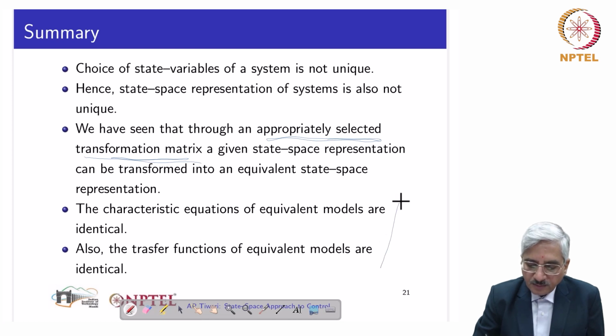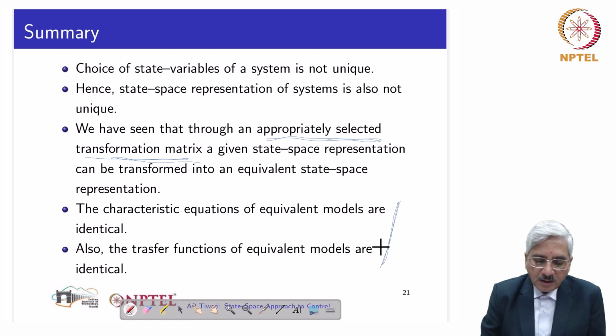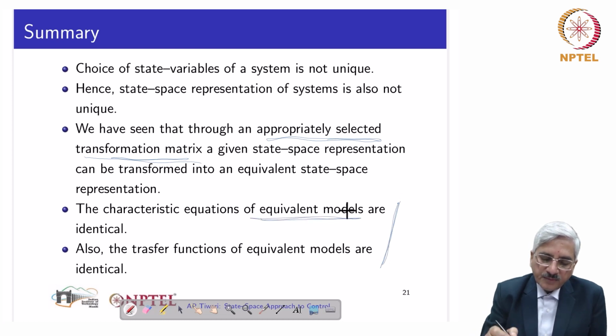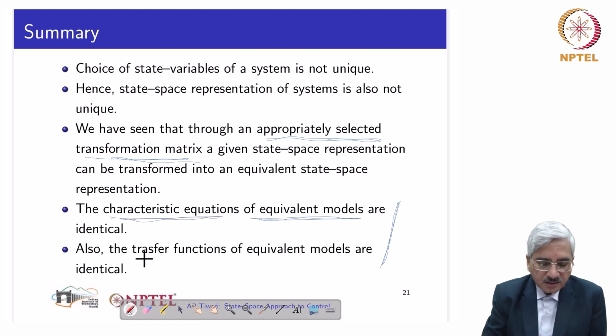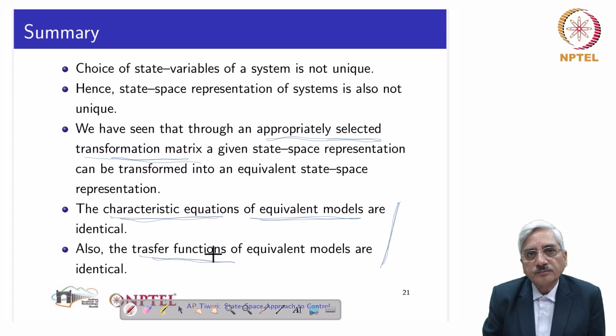However, this is something we have to remember: all the equivalent models obtained through different similarity transformations will have the same characteristic equation as well as the same transfer function, meaning that the input-output relationship of a system is preserved. That doesn't change.